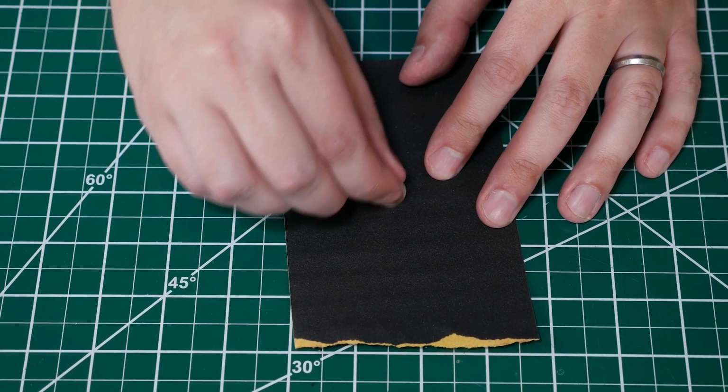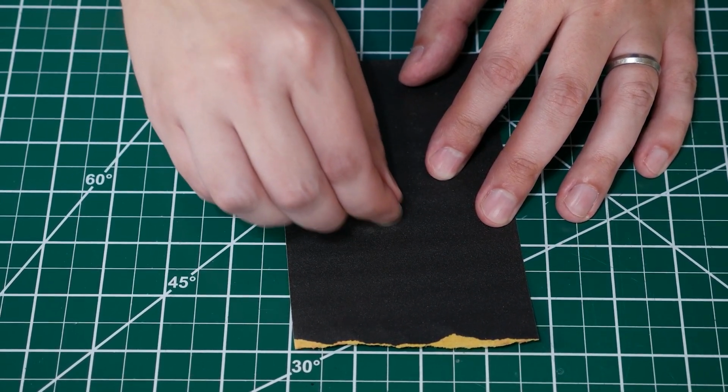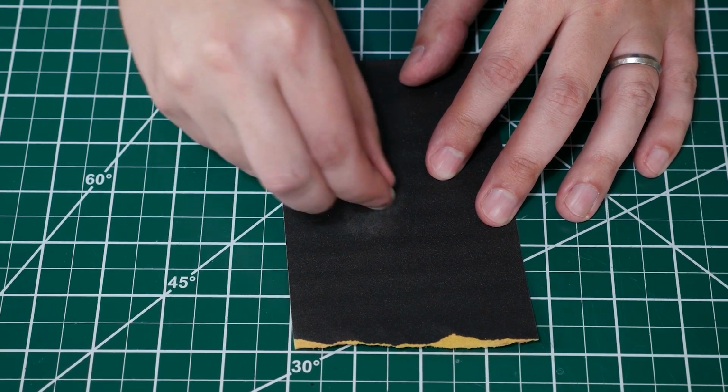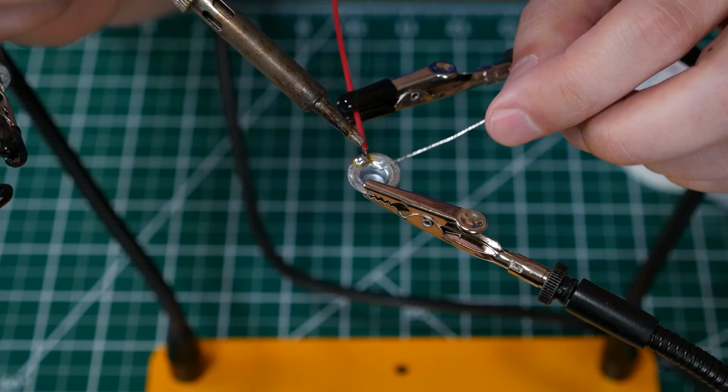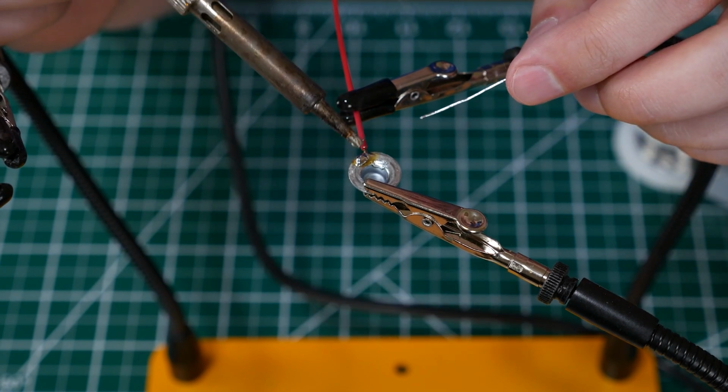I'm pretty sure this is zinc-plated steel, and I found that I have to sand the plating off before it can be soldered. I also discovered that sanding them helps a lot with electrical conductivity. We want to solder the wires before adding the magnets because too much heat can affect the magnets.